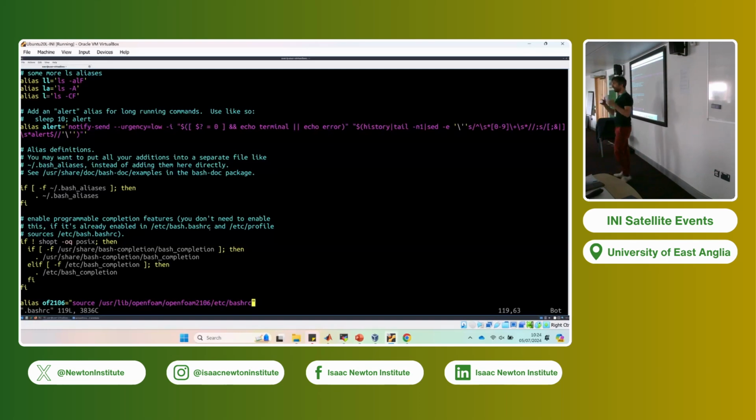You can install multiple versions of OpenFOAM. They will not clash with each other. And then you set different aliases here so that you load only the version that you want to load.